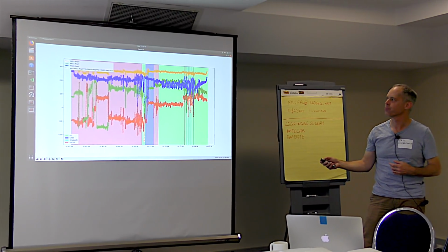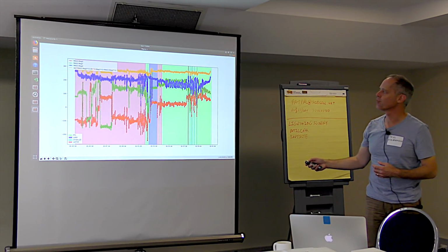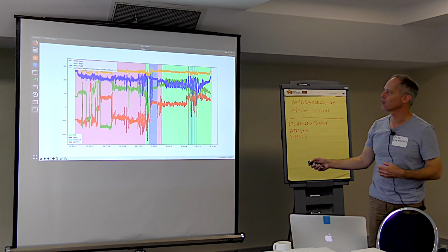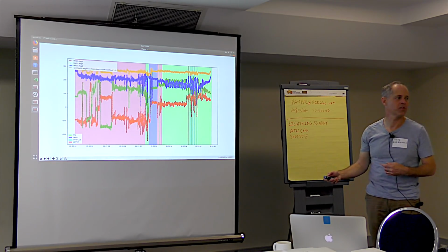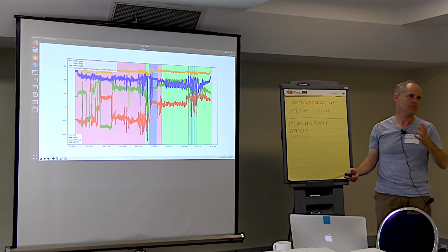It'll be constant. You can see here that we have some variation in the magnetometer, but usually anything less than a range of a variation of 50, which you've got here, that's normal. This is acceptable in terms of magnetic interference. It's around about 10% of the field strength.